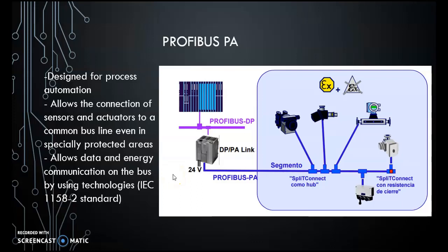Hi teacher, my name is Antoni and I'm going to explain how Profibus PA technology works. Profibus PA is the Profibus solution that meets the requirements of process automation, where there is a connection of automation system and process control system with field devices such as pressure transmitters, converters, positioners, etc. Profibus PA enables the operation of field devices in intrinsically safe areas, as well as the maintenance and connection/disconnection of devices during operation, without affecting other stations in potentially explosive areas.